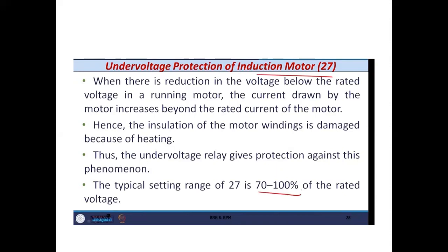When there is a reduction in the voltage below the rated voltage in the running condition of the induction motor, the current drawn by the motor increases beyond the rated current or full load current.